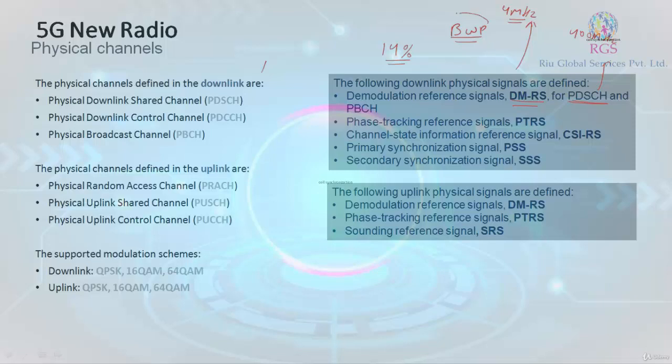So this is the purpose of the bandwidth part. And to identify your bandwidth part's RSRP and RSRQ, we make use of demodulation reference signals. Wherever you have data, wherever you have PBCH, you will also see the DMRS, which will help you identify its RSRP and its RSRQ. So in the planning tool also, you will see RSRP for different channels as well, like SS-RSRP, as it is also known.